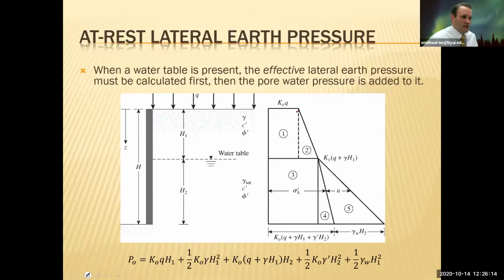This first point right here is represented by your surcharge. This is a uniform load, and it creates a pressure that's trying to push this wall out. Then you've got each of these other shapes to consider, but sometimes it's hard to draw these shapes, so you can simplify them any way that you want. There's no right way to do it.